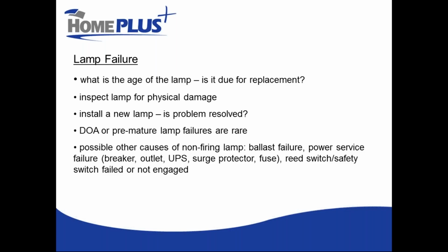And then I can do some chlorine contact calculations for you. We can estimate your baffle factor based on your configuration, and we can determine probably pretty accurately whether or not that level can be safely reduced. And if it can, then we can go to your drinking water officer with a plan, and it doesn't have to be anything too fancy.